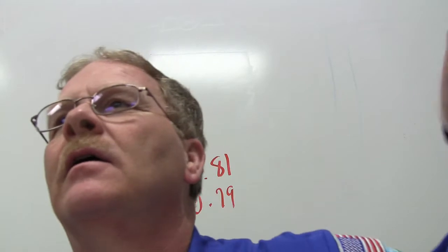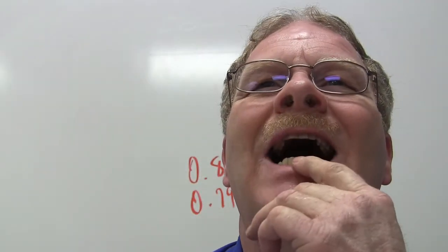Okay, so here we are looking at this thing. As they looked at it, we had fuel trims that were out of balance, and the more they piddled with it and the more they tried to figure it out, they were thinking about doing a smoke test on the manifold. Melissa sprayed some carburetor spray to see if the manifold had a leak, that would show up. And then it started running better. And then it smoothed out all by itself.